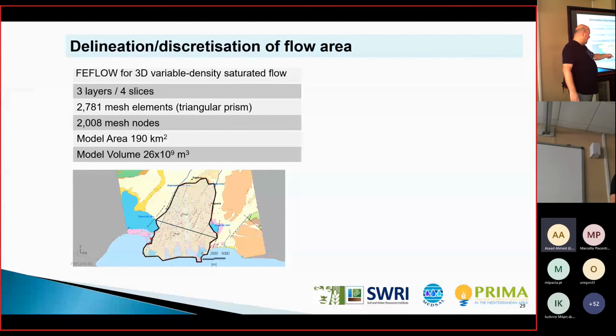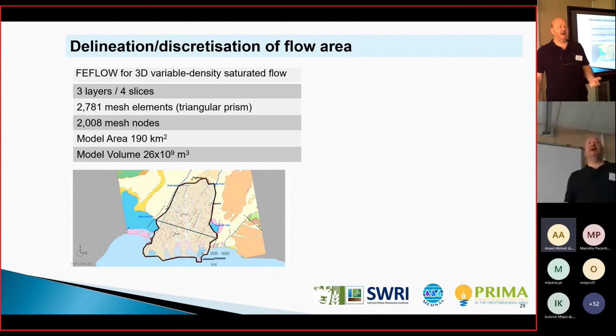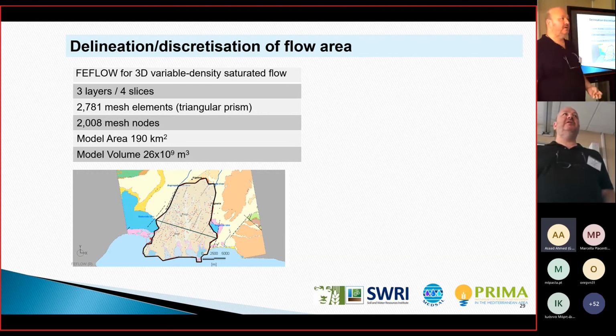And you can see with this line, we divided the model area in two parts. We did this because we would like to apply a finite element mesh in the model area before starting the computation. And we want a denser finite element mesh in the south part compared to the north part, because in the southern part we're expecting higher gradient of salinity variations.